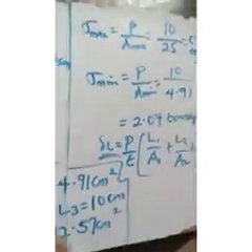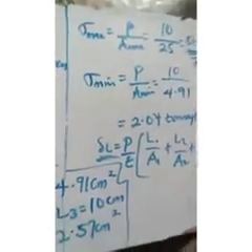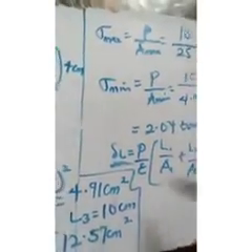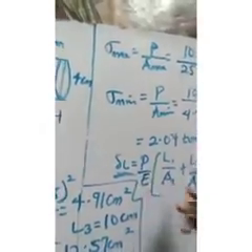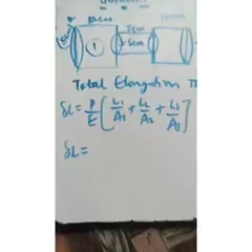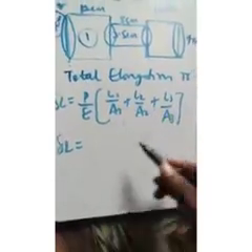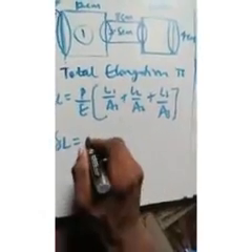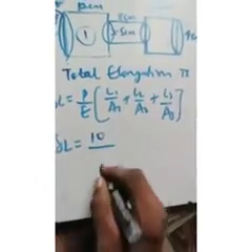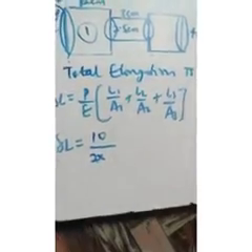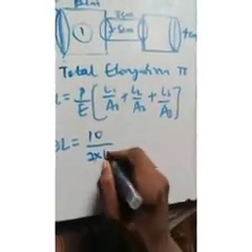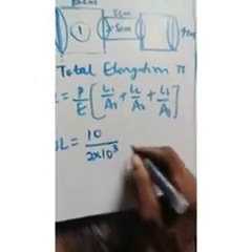What is your L1? 12. Your A1 is 25. Your L2, put it there, and you find your load. You have your elongation, your Young modulus as well. So we have it as this, and now we can just put the values there. So our P, don't forget, was 10, and we're given the value of the Young modulus as 2 times 10 to the power 3 tons per centimeter square.